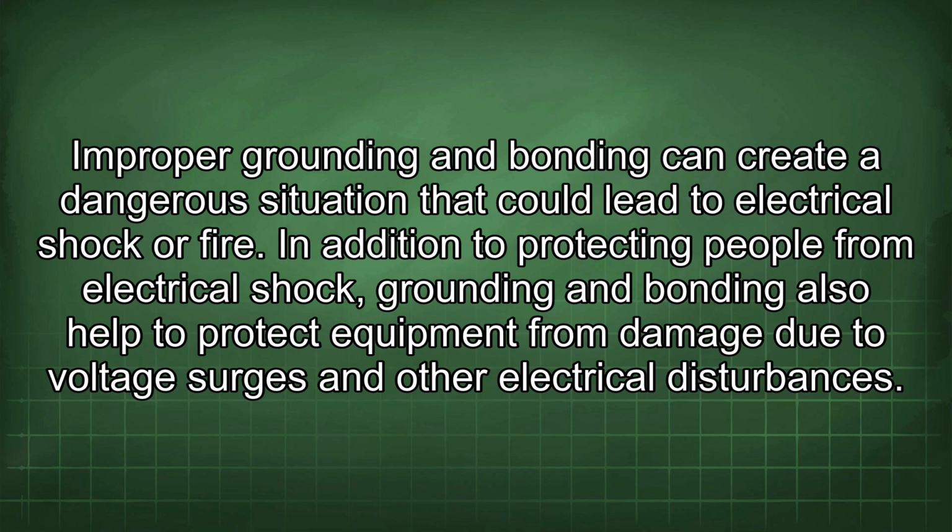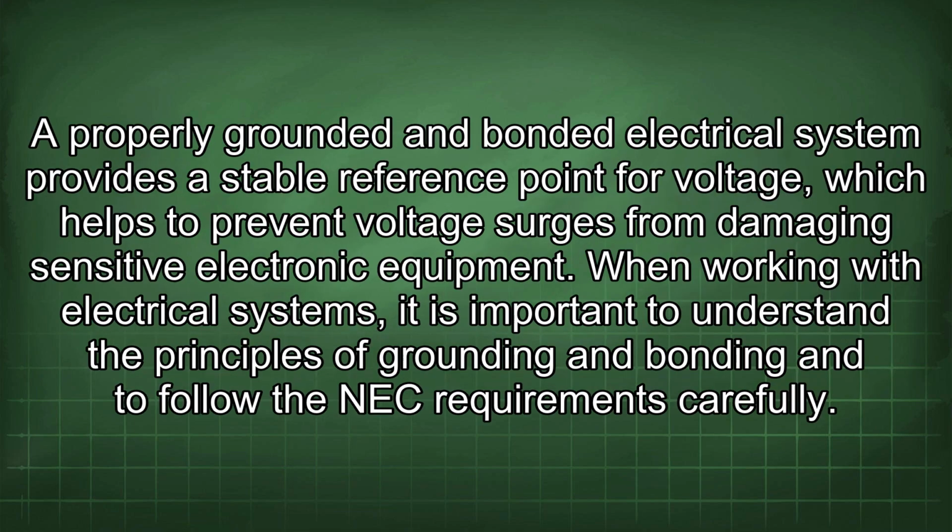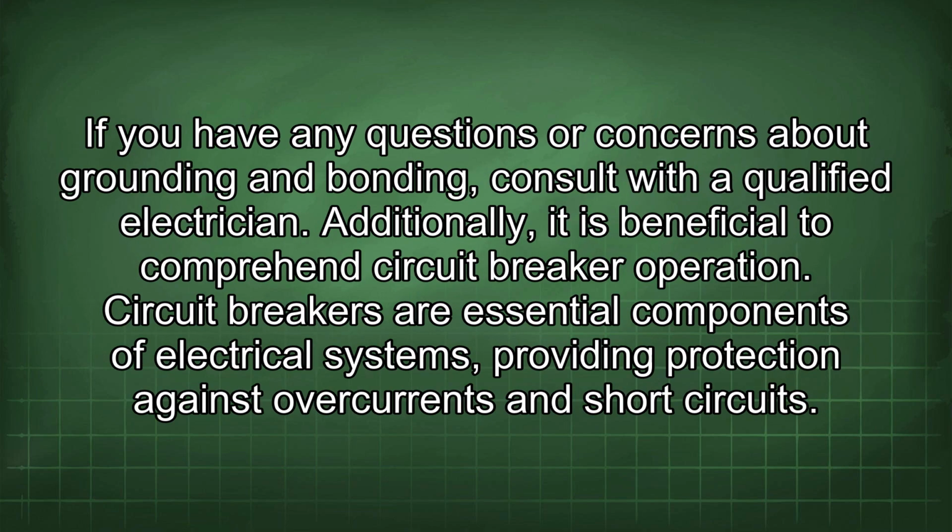In addition to protecting people from electrical shock, grounding and bonding also help to protect equipment from damage due to voltage surges and other electrical disturbances. A properly grounded and bonded electrical system provides a stable reference point for voltage, which helps to prevent voltage surges from damaging sensitive electronic equipment. When working with electrical systems, it is important to understand the principles of grounding and bonding and to follow the NEC requirements carefully. If you have any questions or concerns about grounding and bonding, consult with a qualified electrician.